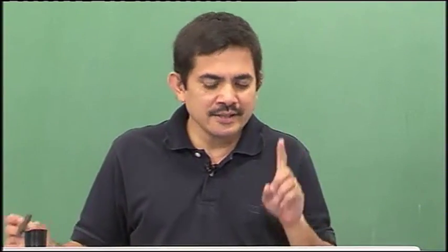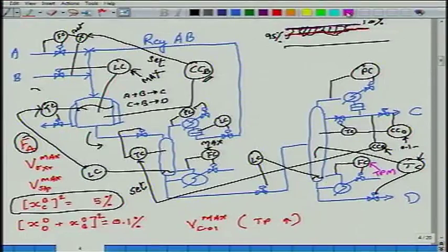Okay, what are the unconstrained? Everything is taken care of. The only independent things are what? This and this. We argued there are 2 degrees of freedom. You see, this guy, the TPM, has been adjusted to get FA. This is really not a degree of freedom. It is not an unconstrained degree of freedom, right. We counted 1, 2, 3, 4, 5. 5 constraints are active, 2 things are left. That means the operator is free to set 2 things. What are those 2 things that he is setting?